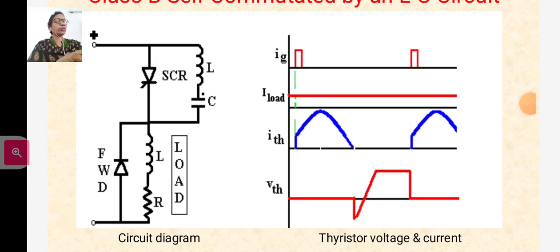The load current flows through the RL load, and it is ensured by the large reactance in series with the load and the freewheeling diode clamping it. A sinusoidal current flows through the resonant LC circuit to charge up the plate of the capacitor C with the upper plate as negative at the end of the half cycle.